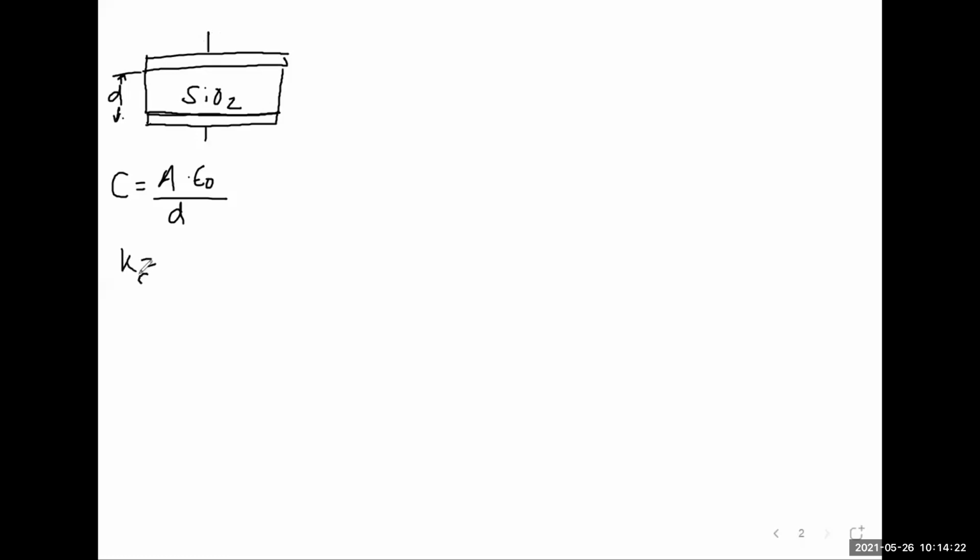The relative permittivity of SiO2 is, let's say, roughly 4. So you had C, what is the multiplying factor to C now if I put SiO2 in between? 4C, correct. So this is 4C now, right? So you go 4 times. This is considered as high K because you're 4 times more than this.